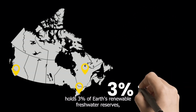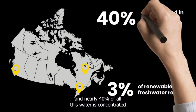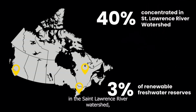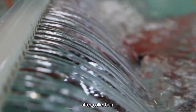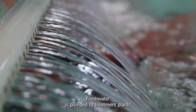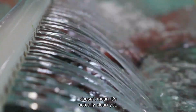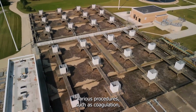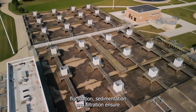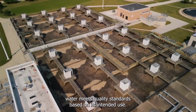Quebec holds 3% of Earth's renewable freshwater reserves, and nearly 40% of all this water is concentrated in the St. Lawrence River watershed, which drains rainfall and melted snow into streams. After collection, fresh water is pumped to treatment plants for purification. Just because it's called freshwater doesn't mean it's actually clean yet. Various procedures such as coagulation, flocculation, sedimentation, and filtration ensure water meets quality standards based on its intended use.